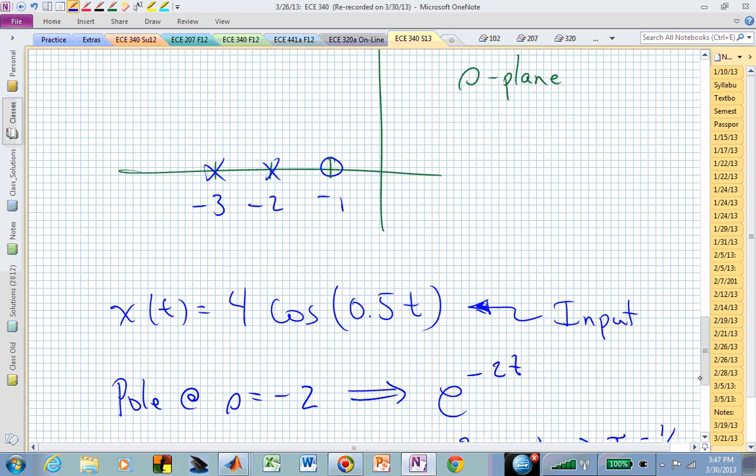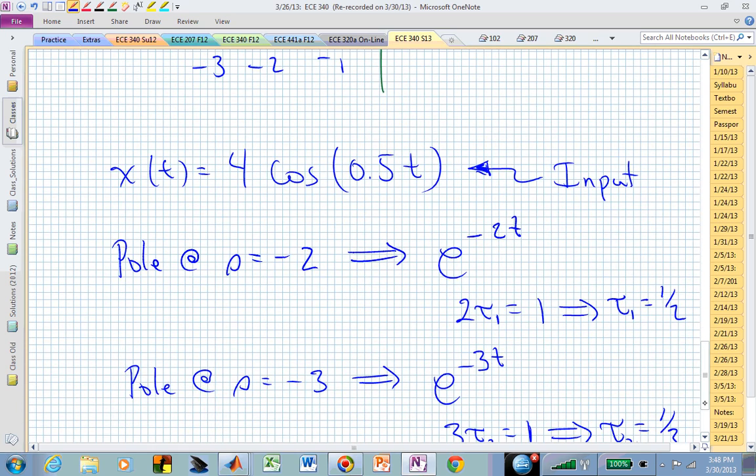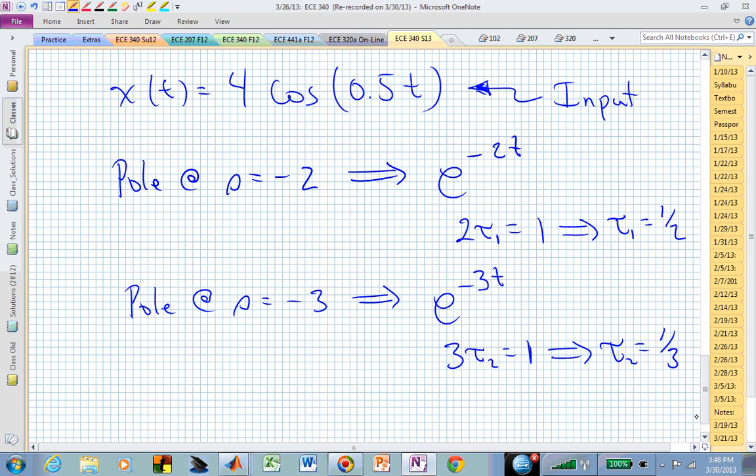For our particular case, the transient is going to be dominated by the slowest pole, or the time constant that's the longest. In this case, tau 1 is the longest, and we would have to wait 5 of those longest time constants, roughly, until we reach steady state.